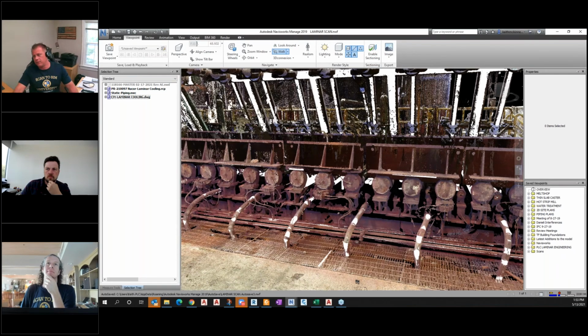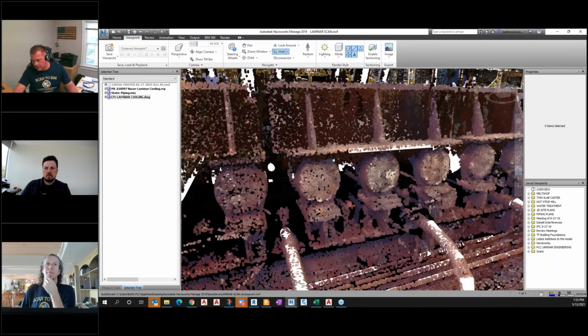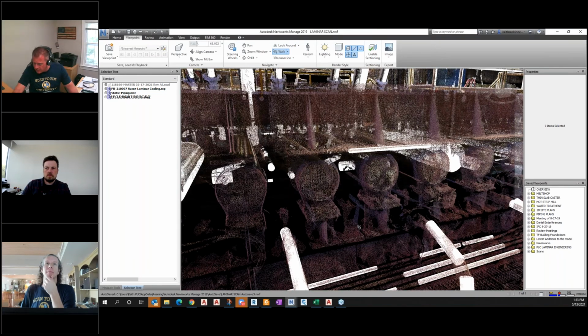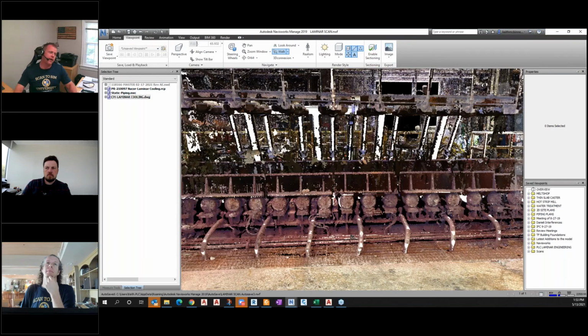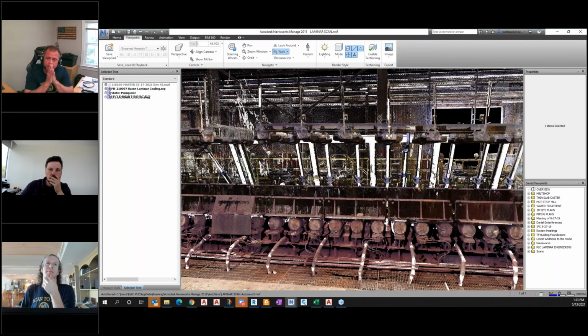And then I will be able to extract all these little tabs off of here all the way down through there. And then I'm going to start pre-laying out all my bolt holes. When they take short shutdowns, we're going to take one section of this out, lay out my bolt holes on the steel, put the old piece back in, and do this up into the shutdown.